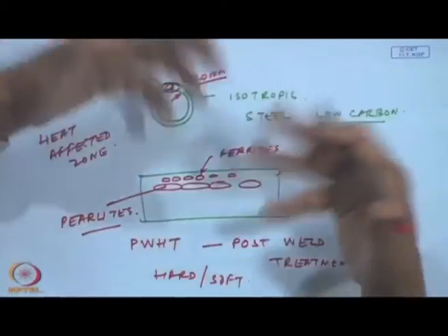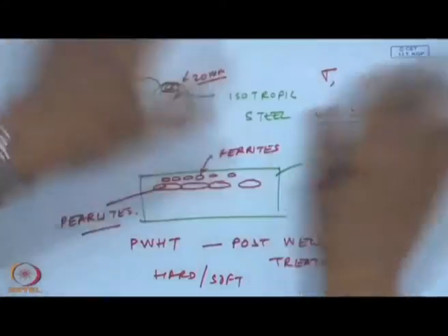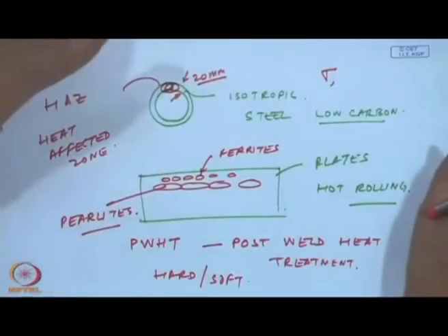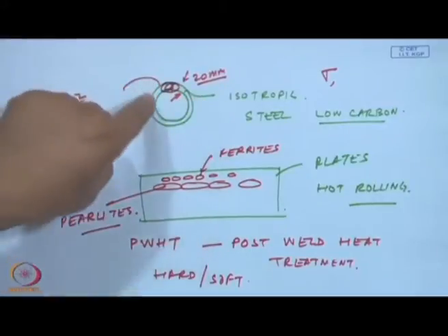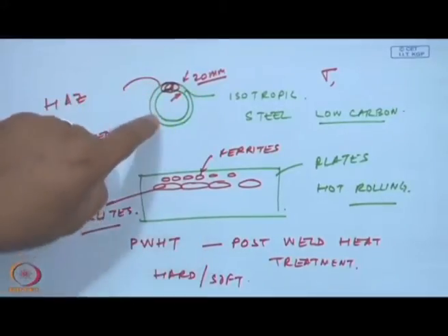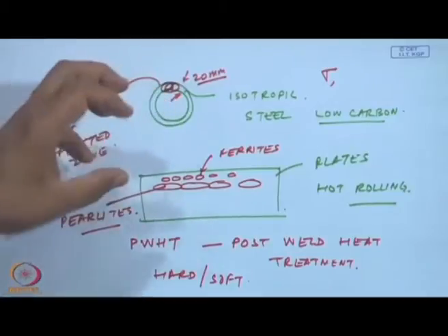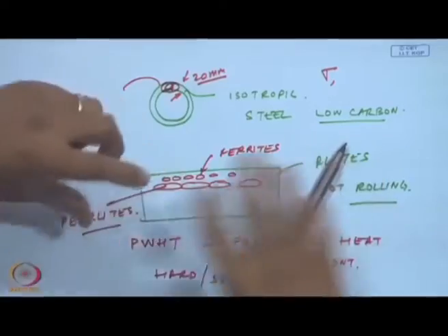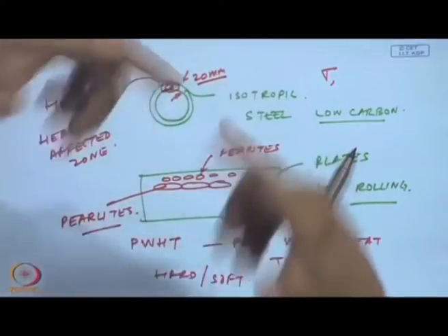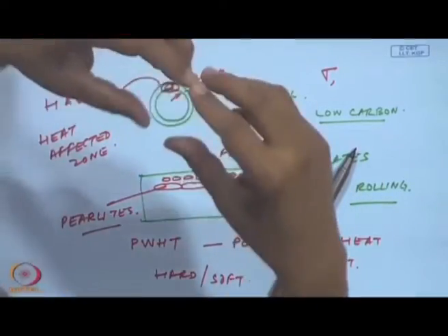For a designer, when I design it, when I take a value of stress, I assume that the stress is uniform everywhere, hardness is uniform everywhere. That is fine, but when I manufacture it, when I have done welding, my heat treatment was not proper. I have artificially created zones of soft material and zones of hard material, and you are rotating a soft and a hard material together. One zone is soft, one zone is hard, and because of this one inherent defect, a crack is going to originate.